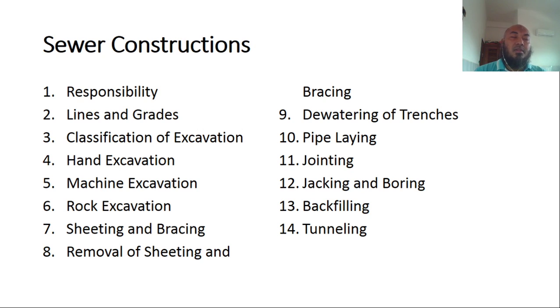You remember we had example one and example two regarding the sewer design. Slope is one of the important parameters to make sure that the velocity can be achieved, more than 0.6 of the partially full flow inside the pipe.